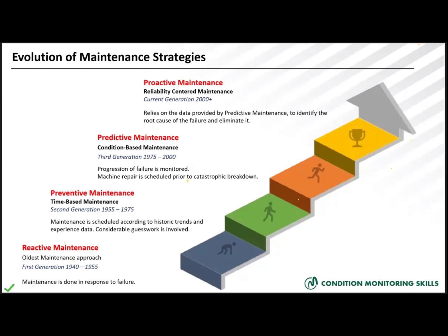So we are studying the main causes of failure, and we are trying to eliminate those causes. The reliability-centered maintenance combines multiple maintenance strategies to improve equipment performance, which means if you are going to apply reliability-centered maintenance nowadays, it doesn't mean that all machinery should be covered with condition monitoring scope. And we will explain this in detail in the upcoming slides.